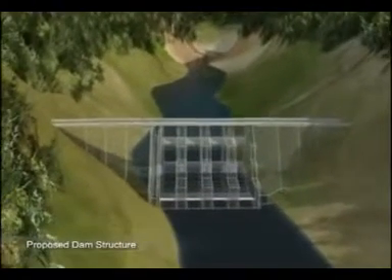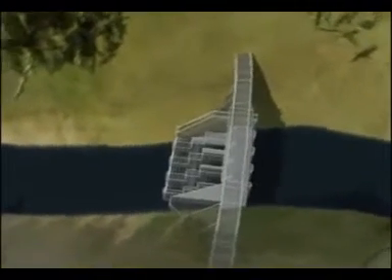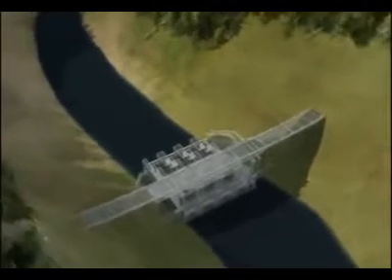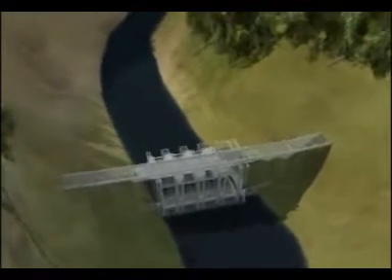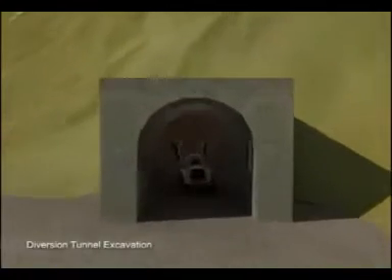Here we can see the terrain and location of the dam. Let us take you through the process of constructing the dam. Before the construction begins, the river flow needs to be diverted to make excavation and construction activities possible at the dam location. This is done by diverting the river water through a diversion tunnel that bypasses the dam location.